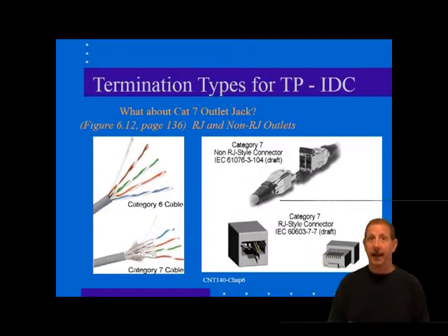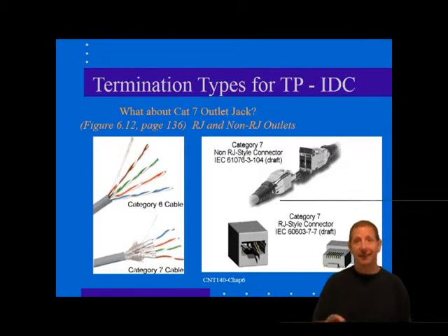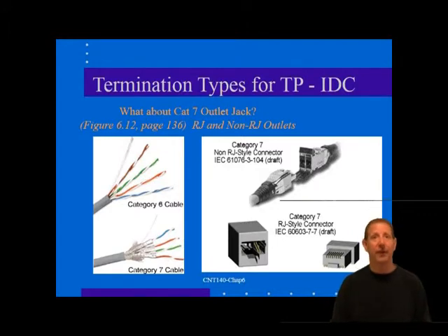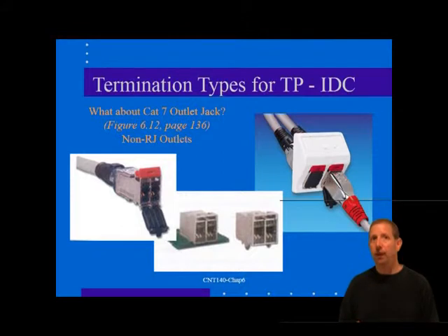Data networking, with its structured cabling, has moved into the radio frequency domain, and the modular plug is a terrible RF connector. With the advent of Cat 7 performance standards ranging from 600 to 1200 megahertz, the old RJ45 just won't do the job anymore. Frankly, it is a connector whose time is up.